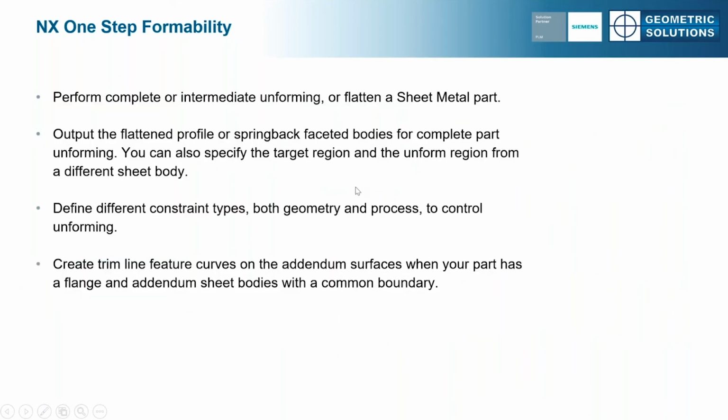So when we think about NX One-Step Formability, the main thing I wanted to highlight is, did you notice just how easy it was to use? It was very fast. And it's not just taking your part and making a blank, but you're actually getting to run some analysis. Is the part you're going to make actually going to work? Because you could take something and flatten it, but maybe you can't actually form it in real life. Well, that's where we're able to test the thickness, the strain, and so on.